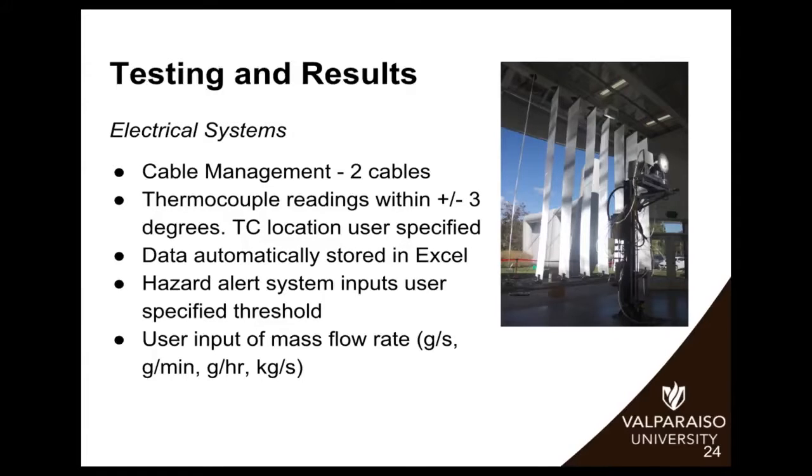Next, our thermocouples, after some experiments with an RTD probe, ended up being within 3 degrees accurate of the actual temperature, which is awesome. Now granted, the temperatures measured were at the highest about boiling water temperature, so about 100 degrees C, but we expect this accuracy to continue once the temperatures ramp up to the 500 to 1,000 degrees C range when the experiment's actually conducted.